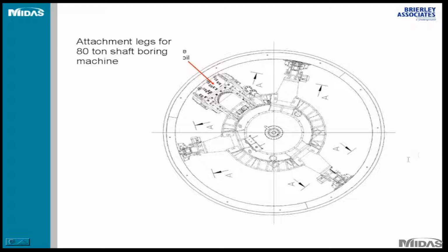So you have an additional wall, I think it was more like 20 inches, in addition to a steel frame, which is also embedded into this cast-in-place concrete wall, in addition to these segments, to account for the TBM forces and the breakout.